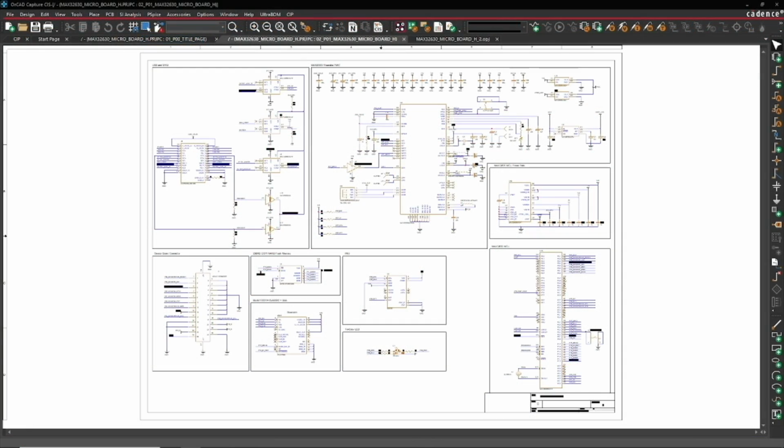Before we even look at the printed circuit board, we need to understand the design itself. When I'm looking at a schematic for the first time, it can be overwhelming sometimes. Every designer has a certain way of doing things, so deciphering the design intent may not be straightforward. Well, I use what I call the input process output method, or IPO method for short, to understand any schematic design. First, I learn all the inputs, things that process information internally, then functions that create outputs.